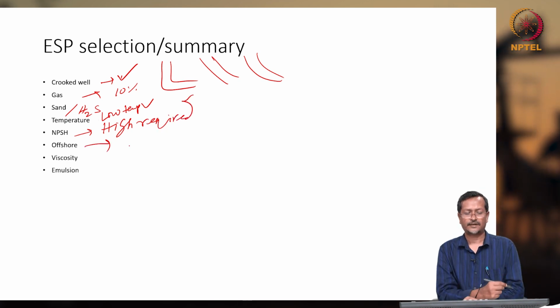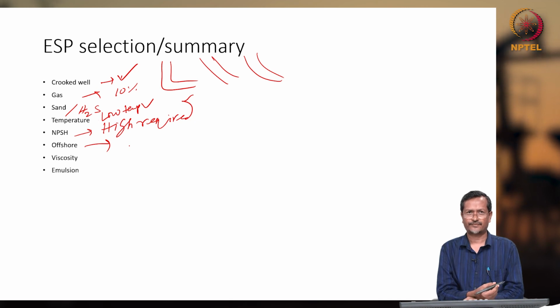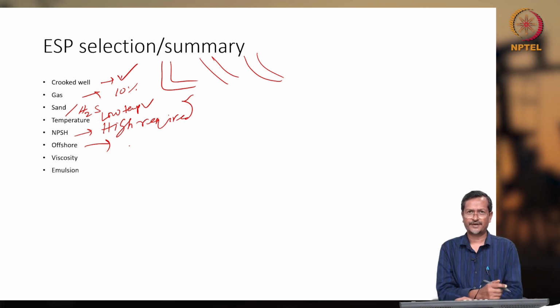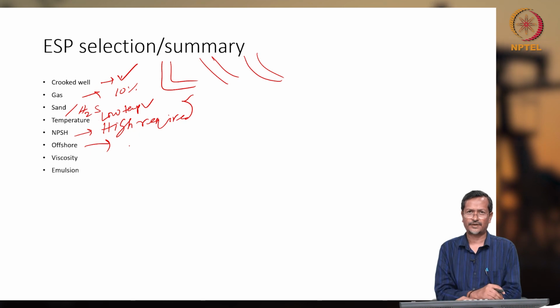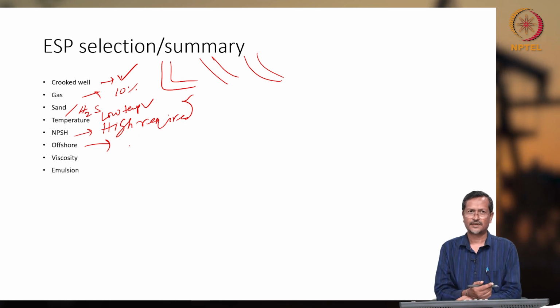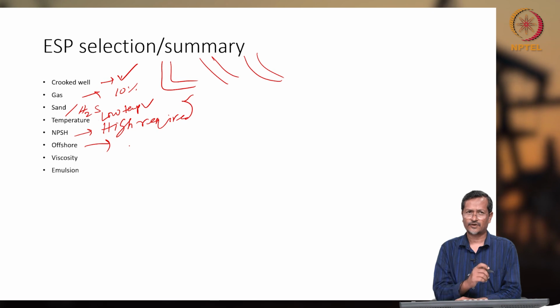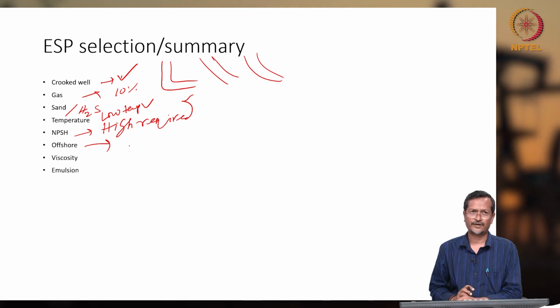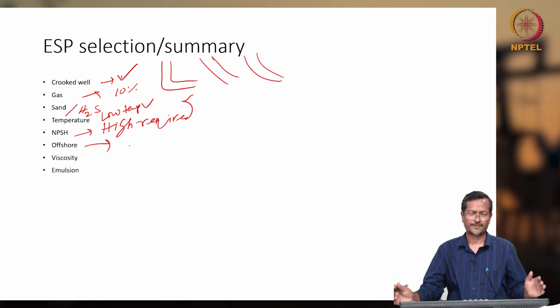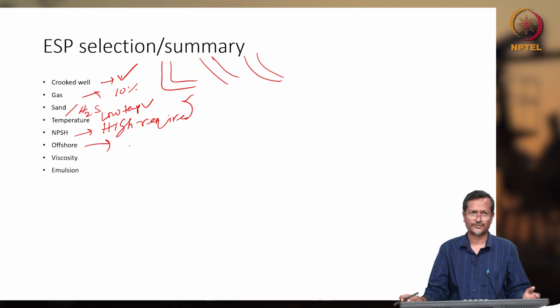Offshore wellbore, ESP does not have a very big surface unit, only a very small unit is required on surface. For example, control box, junction box, transformer. So ESP can be used for offshore application also. But normally people avoid using sucker rod pump for offshore application because of compact spacing, and a heavy unit on the offshore is not good.